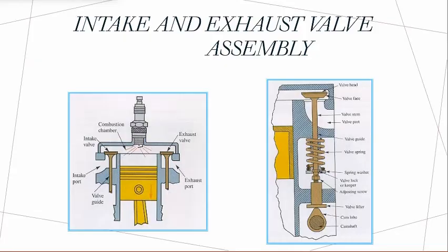The valve arrangement in an engine controls the in and out movement of charge and exhaust gases in the cylinders in relation to the piston position in their bores. Currently, this is located in the cylinder head on all engines. Among the commonly used sleeve, sliding, rotary, and poppet types of valve, the poppet valve is most common because it offers reasonable weight, good strength, and good heat transfer characteristics.